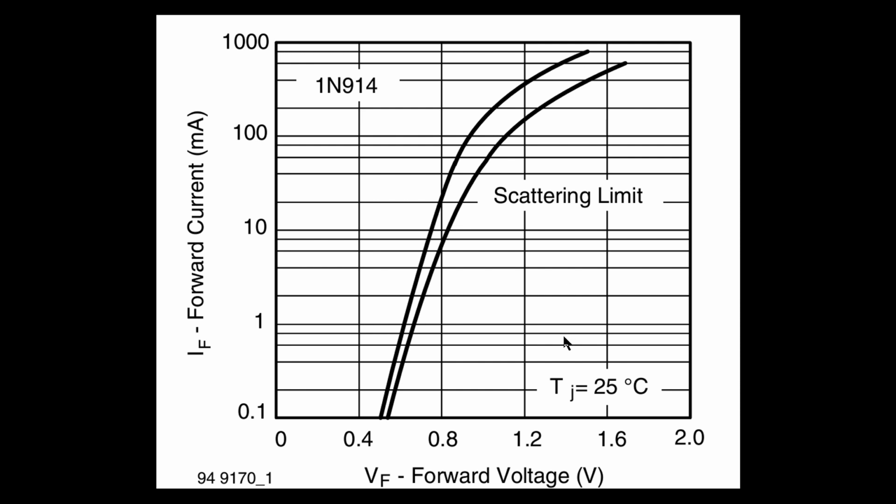So for this reason, we have to do a very important thing when we're testing diodes. We have to set a fixed current, whatever you're going to use. I typically, for ring diodes, I'm going to use 10 milliamps instead of 1 milliamp. 1 milliamp gets really tight, so you're not going to see much. As you go up in current, they're going to show themselves to be more and more different, and so therefore you can get a better idea and classify them closer together.